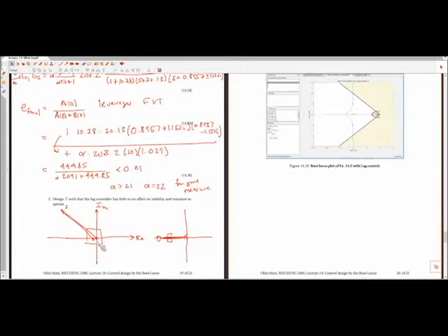So say you work for Motorola, you're building feedback control loops for their cell phones that are electronic devices. Your poles in an electronic device are going to be much, much faster than if you're designing a control system for the temperature control in a room, right? The time constant associated with electronics is so much faster than the time constant associated with the thermal response of this room. Electronic devices are on the orders of kilohertz, megahertz, et cetera. And in the room, we're talking about time constants on the order of hundreds of seconds or something along that line. So very different time scales. So I can't give you a general rule that's going to work for everything, but we can pick some spots and see how they change the total response of the system.